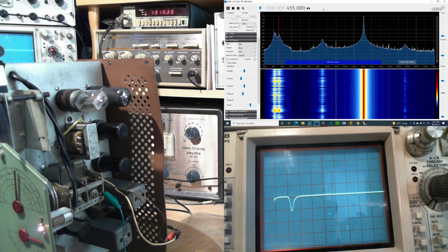That's almost certainly what it is. How could I prove that? Change the effect. I don't want to send more signal to my little SDR radio. I'm going to blow it up. It's already got a lot of signal coming in the antenna. I think that's what I was seeing. My instruments detuned the radio a little bit. The SDR is a regular kind of radio input, a couple hundred ohms impedance. So I stuck a couple hundred ohms onto the circuit here and threw it off. How much more is thrown off?